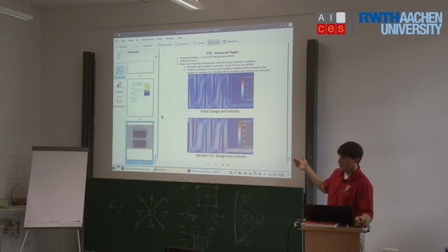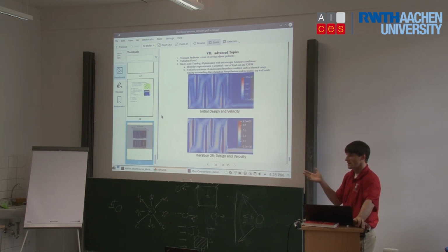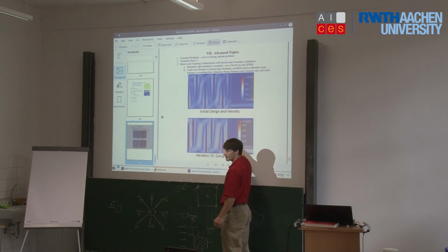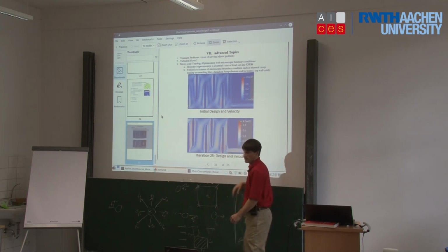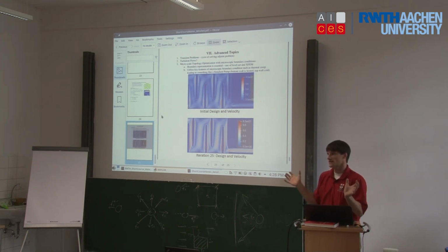And so for this case, there's no way I could solve this problem with a material distribution-based approach, because I would have this blurry boundary condition. All of this happens only because it's along the boundary, and I need the precise gradients of temperature and velocity along the boundary in order to apply this boundary condition. And so I really need an XFEM exact representation of the boundary.